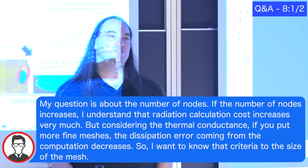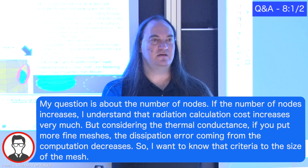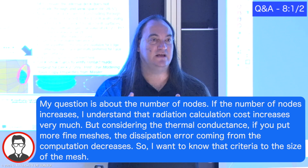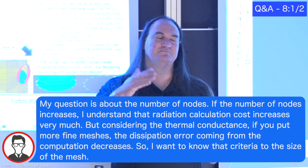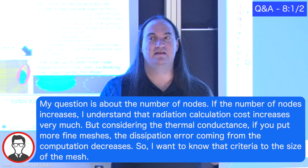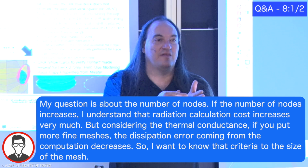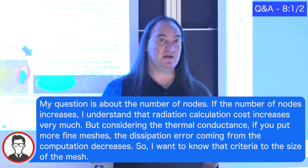That is mostly engineering judgment. As I see it, something that is thin and a low conductivity material, titanium, a composite, I need more nodes for because I have a larger gradient through it. Something that's very thick and aluminum, high conductivity, there's not enough of a difference between the calculation points to say I need 20 nodes here. If over those 20 nodes it increases a quarter of a degree, why do I need all that granularity between it? So it really comes down to engineering judgment.